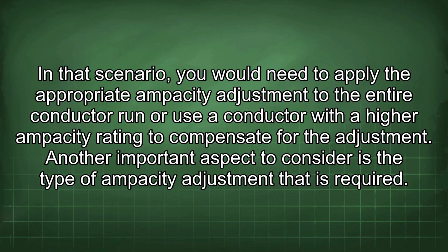In that scenario, you would need to apply the appropriate ampacity adjustment to the entire conductor run or use a conductor with a higher ampacity rating to compensate for the adjustment.